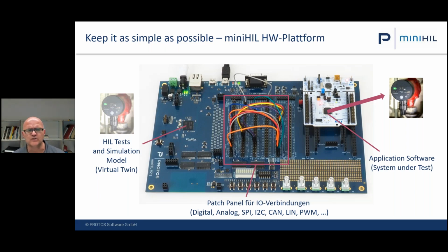So you do not even get to the state where you actually can test the system, because it's not running. So you need to attach a real motor, or in our case here, to simulate a motor or a battery or a bus protocol, because then you can get the system into any state you want. And on top of that, you run your test cases and you can manipulate your simulation for failure injection and so on. So that's the hardware test setup.